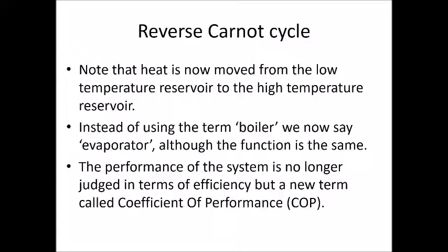So we get very confused customers and we get confused people that work with us because they don't understand it the same way we do. They think that we've made energy out of nothing. And they say, wow, it's amazing, you've got a 400% efficiency. So just to keep us all sane in many ways, we use this term coefficient of performance. It means the amount of energy that's been moved per unit amount of work that's been put in to move that heat energy.